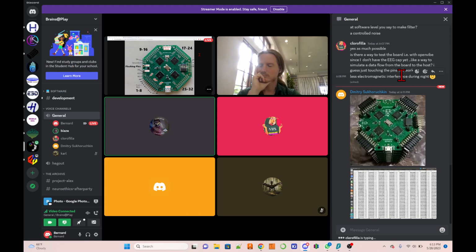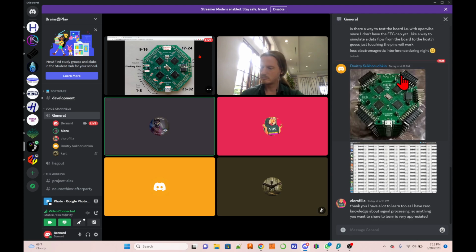But even if you don't have access to a signal generator, you can use a sine wave generation app on your phone. You can have noise or whatever, but if you just want to test a signal without a headset, I plugged an audio jack in and divided it down again, so I had something closer to what it would really be. It's not perfectly clean, but good enough for debugging. Just plug that into the positive and negative pins. I think that should give you something you can play with.